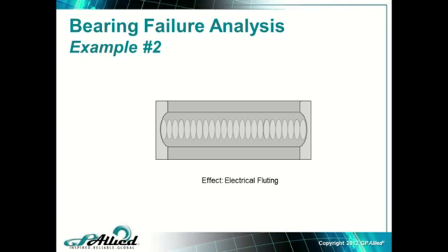Now, the learning point here is, especially with mechanics and electricians and operators and people who walk by these motors on a daily basis, you pull this thing out, you cut it open, and you show them that, and you show them a picture of the corroded wire before it was repaired, and you say, look, when you see this going on with the wire, this is what's going on inside the bearing. Right? These are connected. That's not just the, oh yeah, one of these days we'll have to come by and fix that ground wire. It actually matters a lot. And so we can connect some very nice dots in people's minds in the plant by being able to show them these broken bits and show them these bearing failure mechanisms and connect them to actual real-life practices like the last example or real-life conditions like this example.